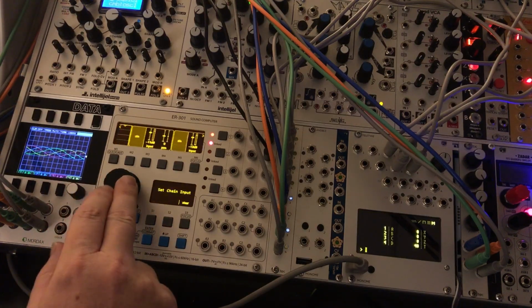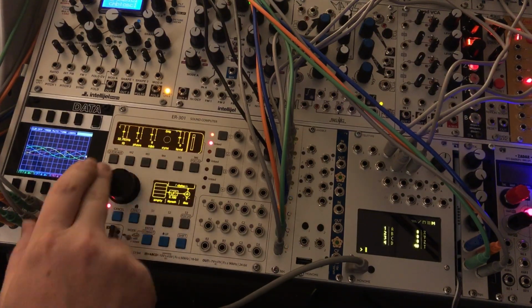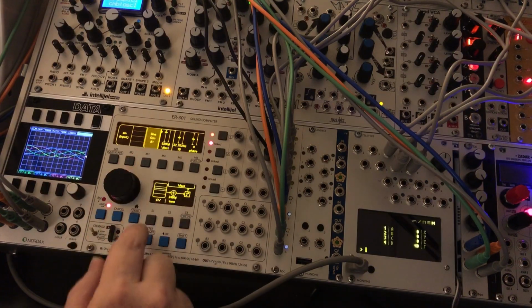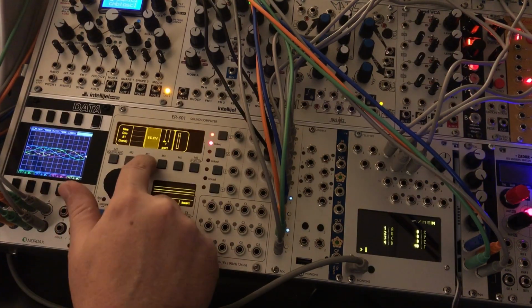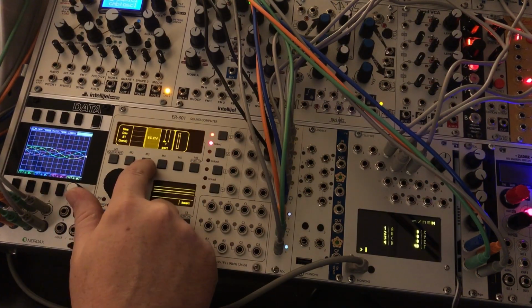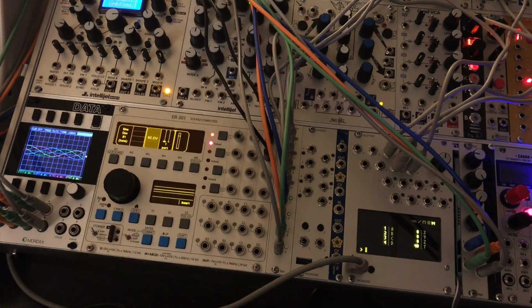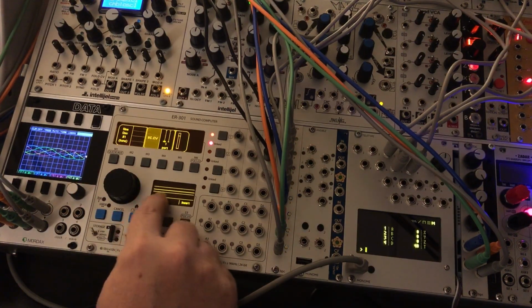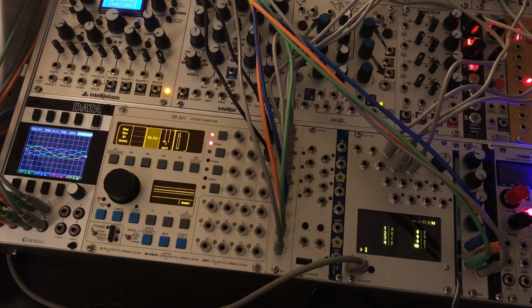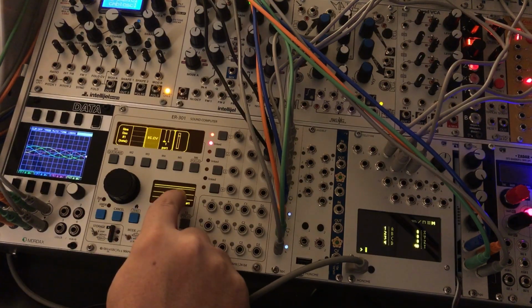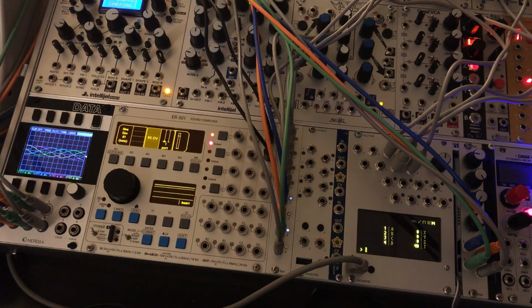And then the pitch is being controlled by these SC.CV units on ports 1 through 4. So we can see here, you can kind of see this line above the center. This is on port 1. So if I do SC.CV1 and I set that to say 7 volts, we'll see that line jump up above the 5 line here, so it's set to 7 volts. So that's kind of how we're controlling this patch.